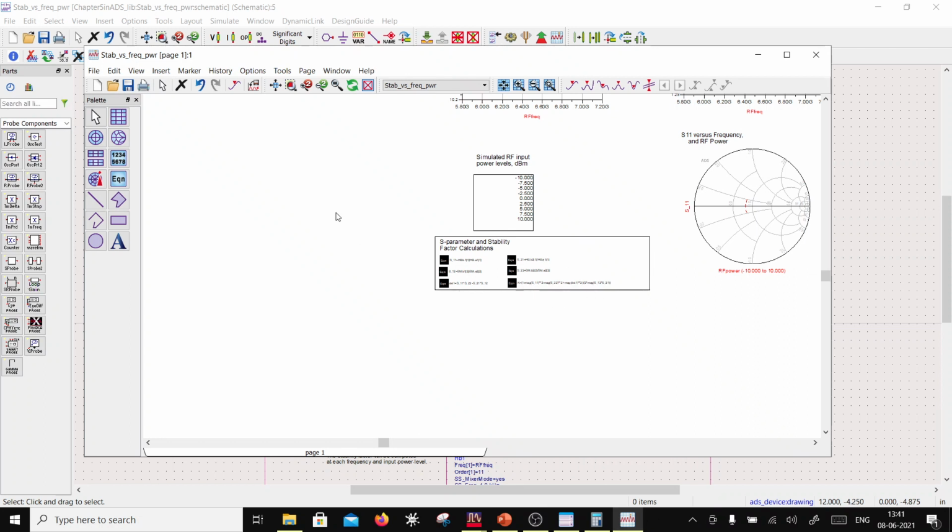So whenever you run the simulation, it will compute and give you here. But when you do it in the data display window post simulation, then for every data set you will have to recreate it. When you change the data set over here, these equations will apply to the new data set. But if you want to compare the two data sets, then you'll not be able to compare them because these equations are valid only for the default data set.